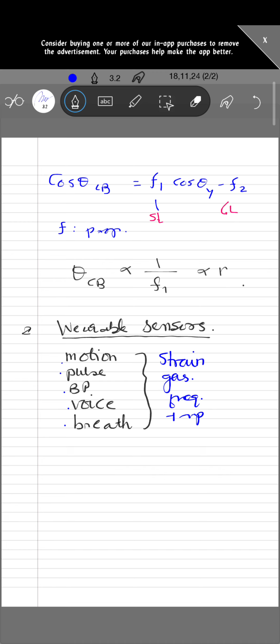Now, why does the necessity of super hydrophobic material come into the picture? The reason is that the body, while changing its position, can sweat, or there can be other hindrances, environmental changes like absorption, humidity, temperature, which may change the surface of the sensor or the substrate on which the sensors are mounted.